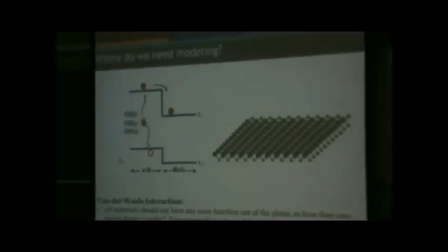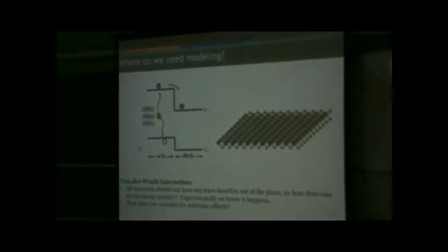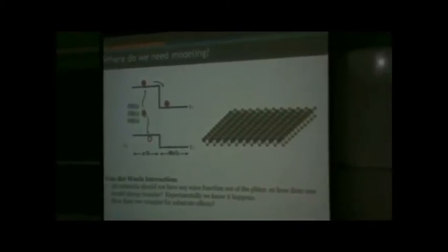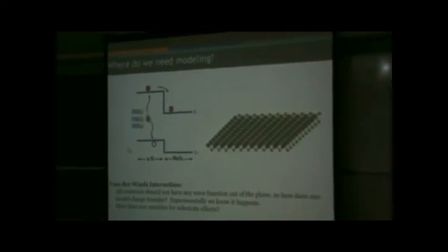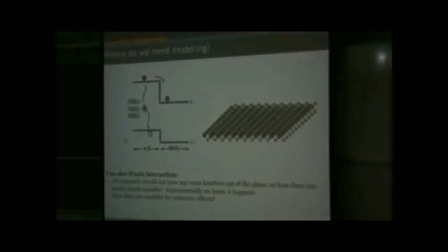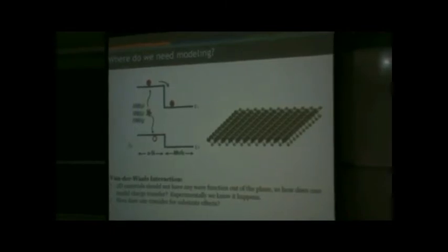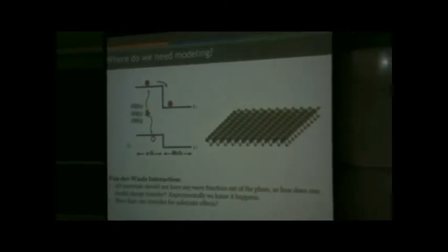So what do I mean by that? I look at the ionization potential of amorphous silicon and MoS2, and we believe that I should get a PN junction. We put it together, we get a PN junction, everything works beautifully. But we don't know why this works. The reason is that MoS2 is supposed to be a 2D material. The only interaction with the amorphous silicon should be van der Waals. So we don't know why there is a significant amount of charge transfer at the interface.